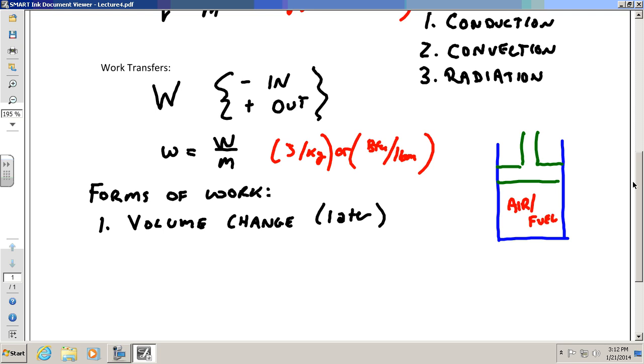And then what happens? If it's a spark ignition engine, you have a spark, right? And then what happens? You have an explosion, basically a controlled explosion inside your engine. You have a lot of them, right? That's how many cylinders you have and the speed and all that stuff, but okay. What happens is that when you have the air-fuel mixture and you have that spark, you have what we call expansion. You have a significant volume change in that cylinder.